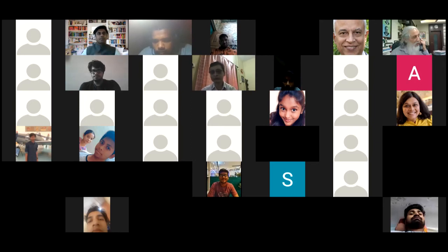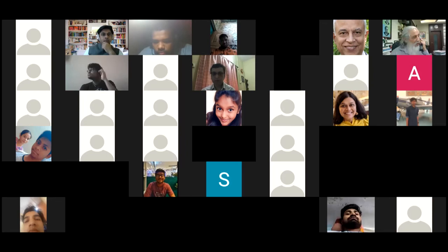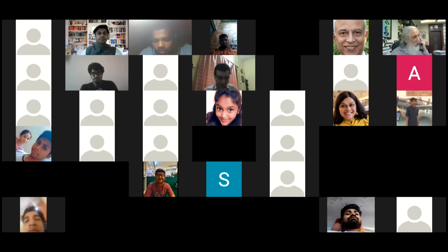And then there is also something called burn-in testing. Burn-in testing means that you leave the device or your circuit to operate maybe for days, and then use some kind of software to extract the best results that you get. That is another time-consuming process. Overall, I have seen that testing of RF circuits actually takes more time. By more time, I mean sometimes it can take 1 year to test. That is a very important part, and for that we need good equipment also.